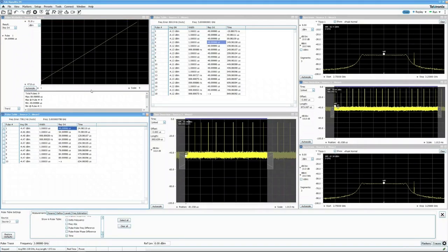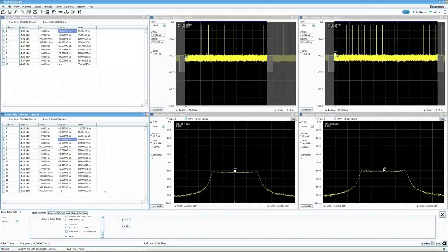And it is flat for channel 1, so let us change it to source 2. Let's select the PRI for source 2. As the target is moving, here we can easily see that it has a certain slope, and the slope is 5 microseconds. So this way we can visually see the characteristics of the radar target simulator from the radar.